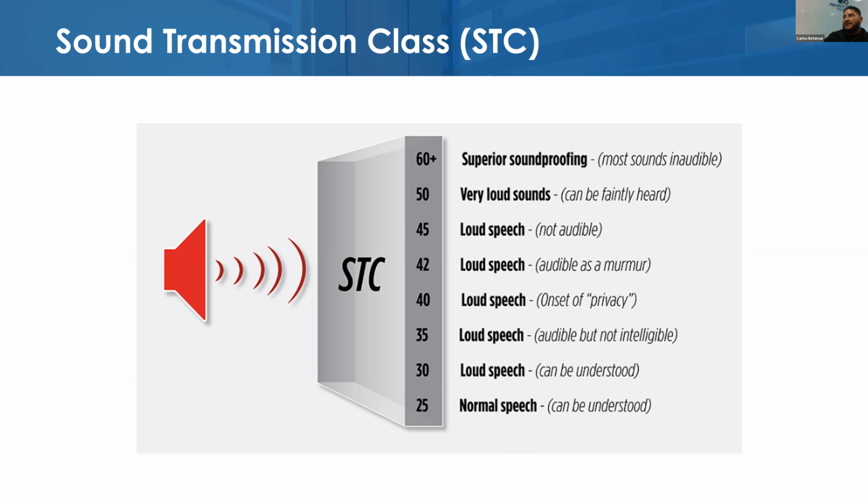Higher STC ratings can be achieved. You just have to increase the thickness of the glass on either side. So 39 is going to be about the roundabout for these laminated products, or in this case the 1/4 inch with the 1/2 inch laminated.